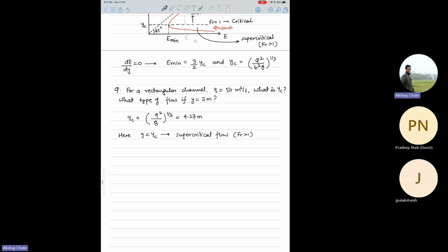At one point, your open channel flow will turn supercritical, and if it faces an adverse pressure gradient downstream, such that the downstream conditions cannot maintain that velocity in the supercritical region, it will undergo an abrupt change in the velocity, like a shock. In fluid terms, we call it a hydraulic jump, and there is a derivation for it.